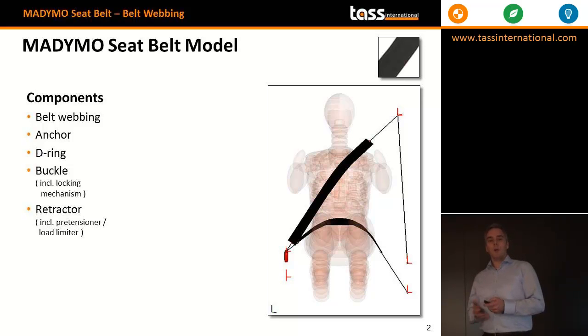In MADYMO, if you want to represent this, you can for the sensors use the element class sensor. So you have sensor body linac, for instance for detection of linear acceleration of the vehicle, or sensor belt or sensor joint if you work with a multi-body chain. For control in MADYMO you use switches. We have several switches, switch time, as we say, for simple time control switching predefined.